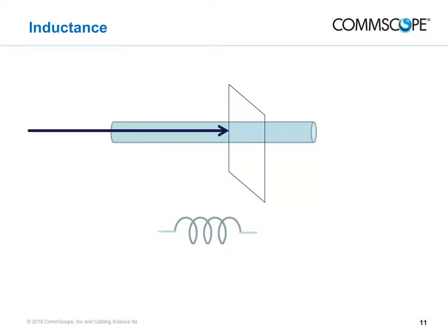Inductance is the property of an electrical conductor where a change in the electric current through that conductor induces an electromotive force, EMF, that opposes the change in current. When only a single conductor is involved, this phenomenon is technically called self-inductance. The induced EMF is due to the change in the magnetic field surrounding the conductor that occurs as the amount of current flowing changes. Any device, such as a coil, that shows the effect of self-inductance is called an inductor.